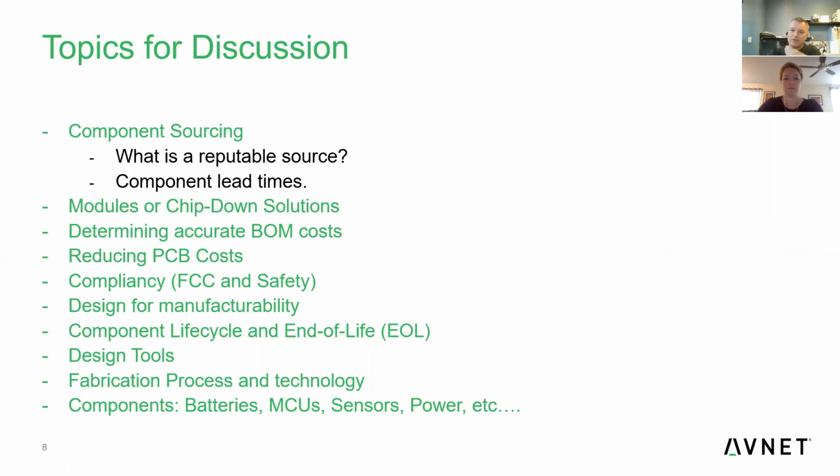It's more stringent if you are an intentional radiator. If you have a radio transmitter in your product, whether it's Bluetooth, BLE, or Wi-Fi, it tends to complicate the certification. And when I say complicate, that should also translate to dollars, because that just means there's more testing required and more paperwork that needs to be filed.